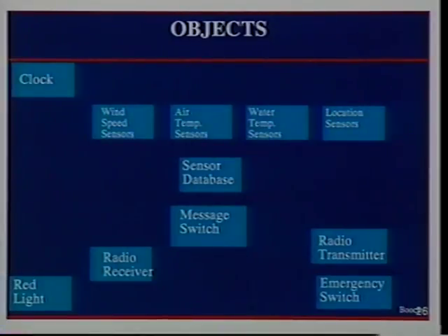The three interface functions that we need to provide for the wind speed sensor are the following. One is get pulse. That means I send a message called pulse. Every 30 seconds I send a message called pulse. And when I send a message called pulse, associated with that message, I can have a procedure called take sample, which will be invoked, and that will take the sample. Once it takes the sample value, it can put it into its attribute called value.